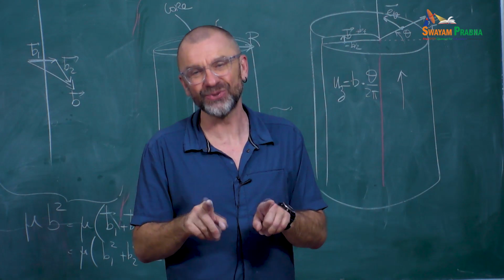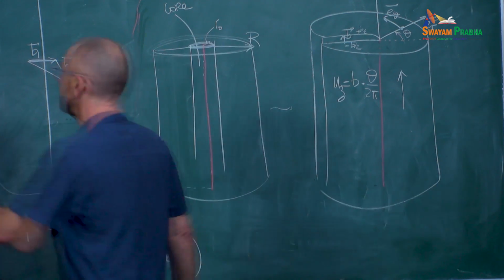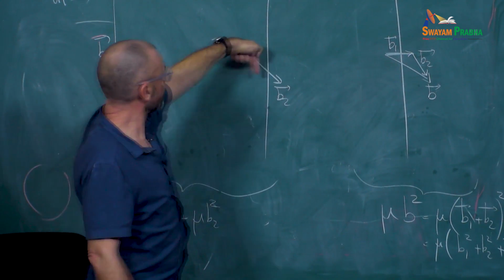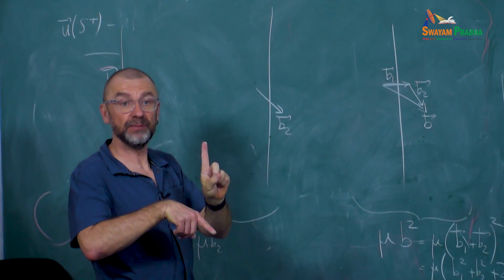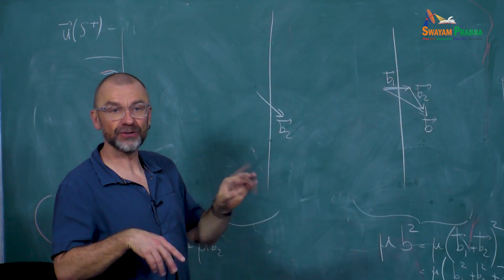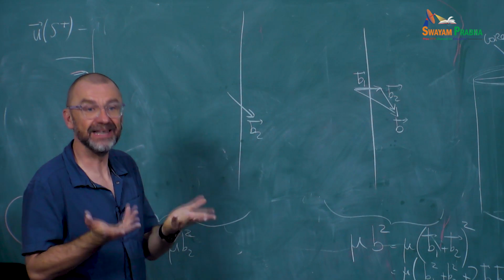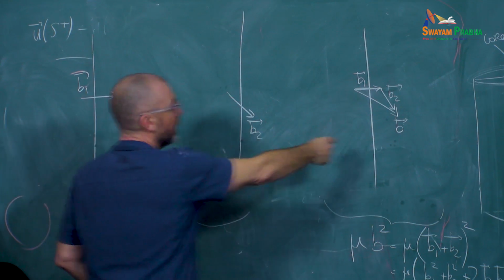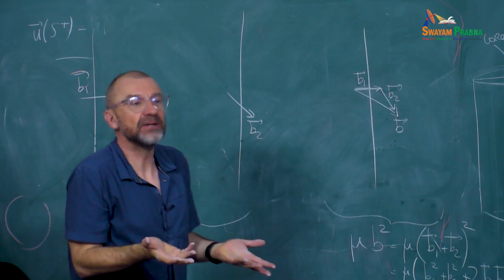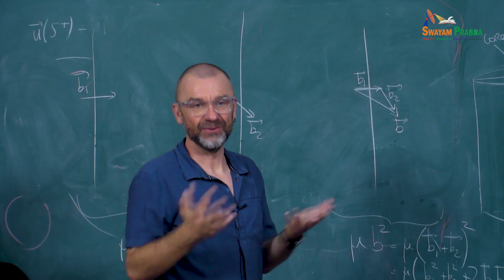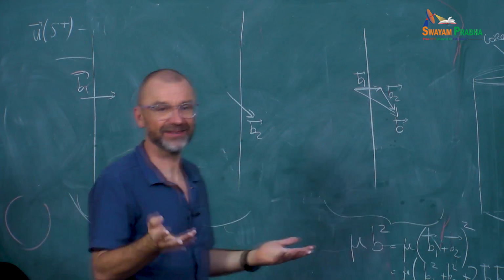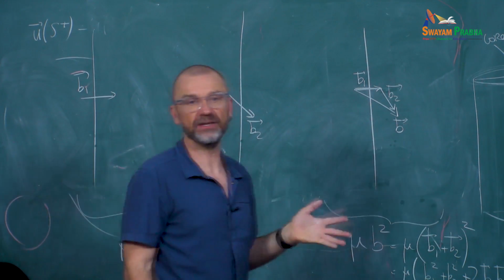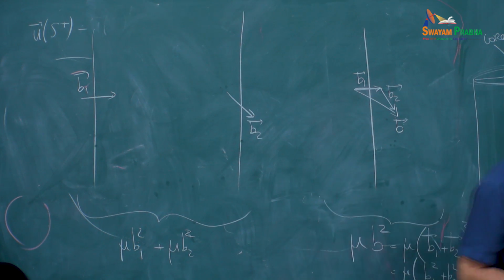It's the case of edge and screw. So if this is an edge and this is a screw dislocation, then one will be perpendicular, the other one will be like this. So the two Burgers vectors will be perpendicular. So the dot product will be 0. And so it will be the same energy whether the dislocations are far away or they are together. And that's because they are not interacting. So since edge and screw dislocations do not interact, there's no difference in energy. And so the rule also works in this case, right? And that's why I was confused earlier.